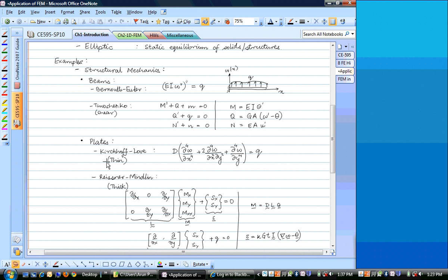But truly the first PDE that you will see, one of the first that I'm mentioning here, is this plate equation. So how many of you have seen this plate equation before? Okay, very few. So this is what is called the Kirchhoff-Love plate theory, and this is very similar to Bernoulli-Euler beam theory. In the Kirchhoff-Love plate theory, you do not have any shear deformations again. All the deformations are in a bending state.